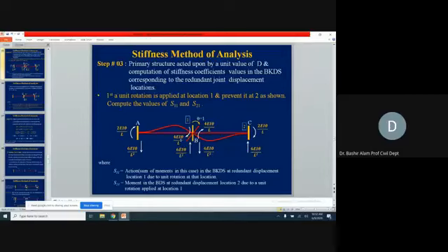Whatever the direction of theta is, that will be the direction of this moment produced. Now, to the far end, it will be carried over by half. The carryover factor is half if the far end is fixed. So because of the half, it is 2EI theta divided by L. The sign will be the same as on the near end. It was clockwise, so this is also going to be clockwise. We will prove all these numbers in a moment.